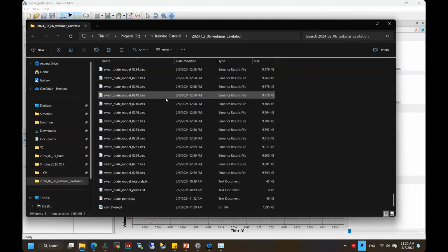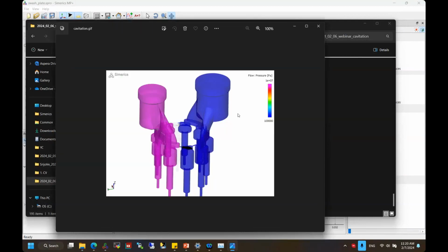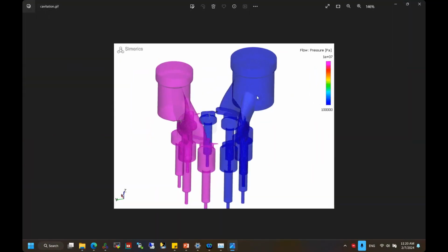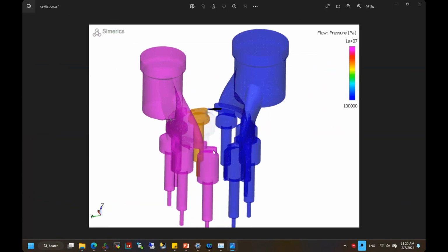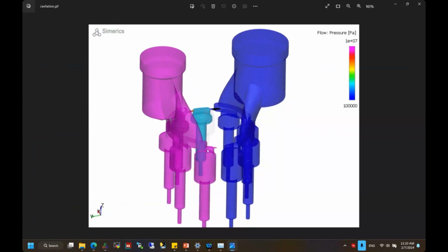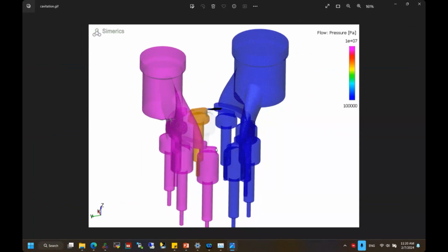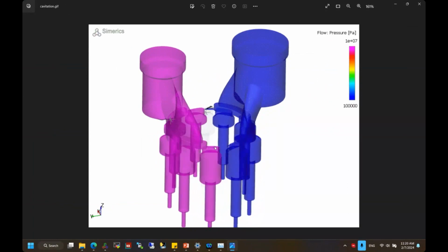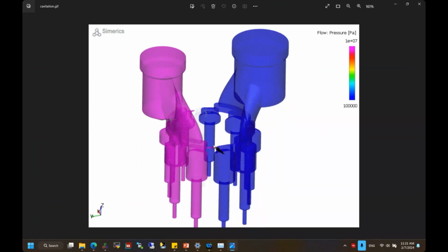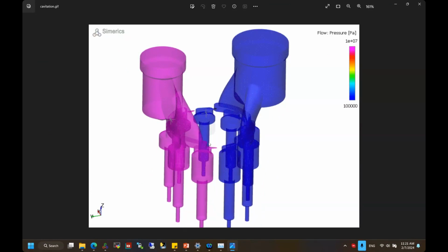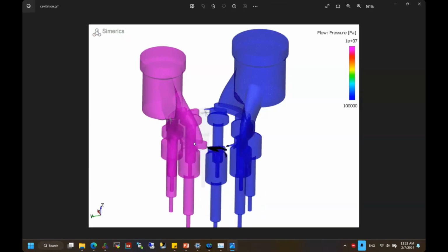So we have this animation. Let me quickly play it, and it essentially shows you the pressure distribution along with this cavitation. You can see the cavitation happens near this pressure relief groove. But another thing is, if the bubbles shoot into the piston, the damage will be maybe not so significant. But if the cavitation happens near the groove, you will probably end up with damage on this valve plate, as shown in the picture Terence showed earlier.